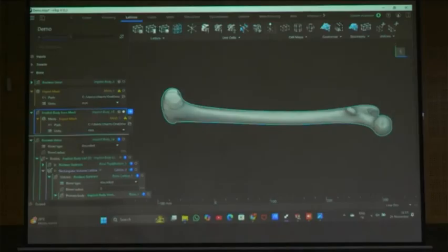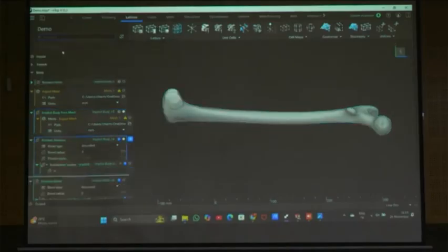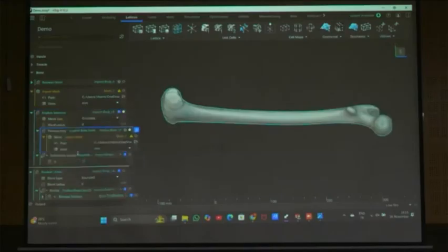How can we do it? Boolean subtract. My primary body is this one only; in this I need to do the operations, so that is my primary body. See, the icons are there, I can drag it and place it here. The remaining blend radius I am not exploring, you can find it in the help also. I will keep this the same. So I will subtract with the plane. The subtraction body is the plane, and I am applying a subtraction with respect to this plane, so this body can separate from the primary body. So I will take a plane from normal.